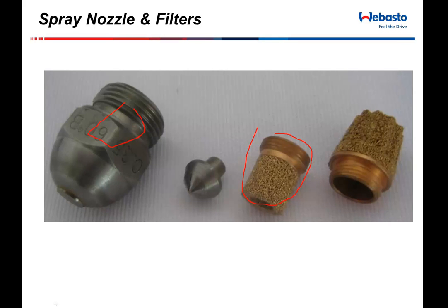You can attempt to clean them, putting them through a parts washer. I would recommend soaking them overnight in something like WD-40, something which has a little bit of lubricant to it to keep it moist before putting it together.